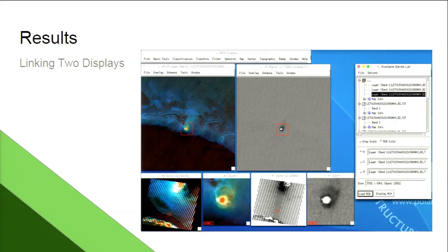Okay, but this had a video of how the information was processed. What had to happen was, through my first time using the floating algae index, I didn't get very positive values. I didn't even really get an index. It was very, very small numbers, and I was wondering what was going on there. Well, what happened was that I had to convert the reflectance values into radiance values first, and then use the band math operation in ENVI to create my floating algae indexes, as well as normalized vegetation indexes. So here are the results, and most of my videos showed how those two images were linked together.